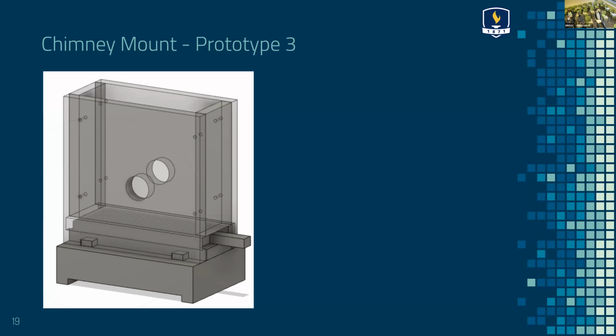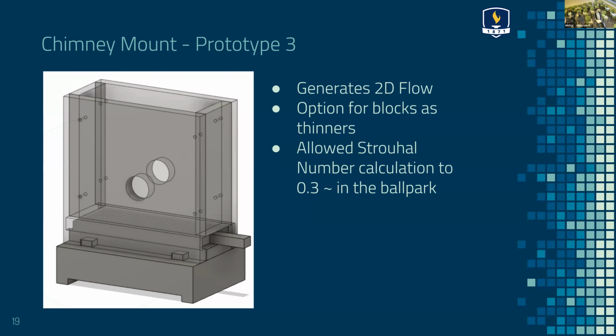In this prototype, on the inside of the mount, we put in a fillet. So it's rounded to try to drive flow only up this way into the shaft to create a 2-dimensional flow pattern, because once you start getting into 3 dimensions, we start getting extra noise like we were seeing on the previous slide. And this is the one that worked.